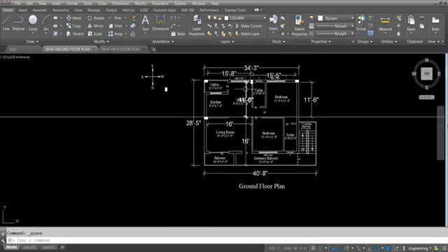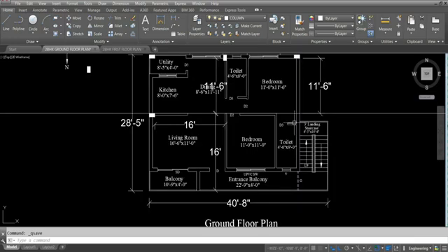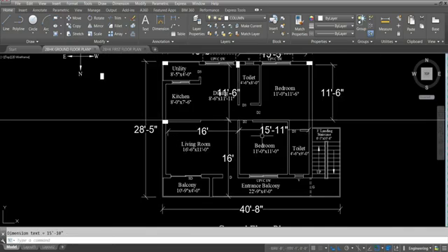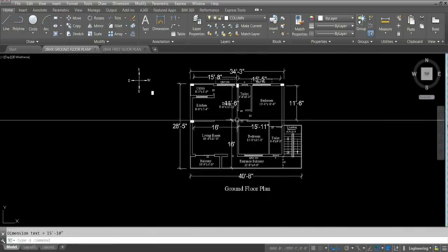Next, this column. To this column, load is coming from 4 sides, from 4 columns. Okay, load of beam, load of column, load of roof slab, all load will be coming from 4 sides to this column. So for this it is 16 feet. Okay, 16 feet minus 15 feet 11 inch is 1 inch. And this side, 16 feet minus 11 feet 6 inch, is 4 feet 1 inch.